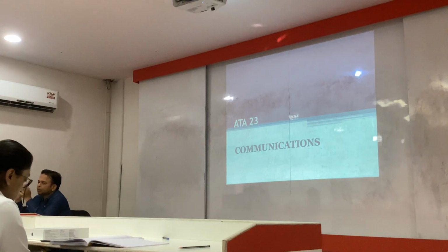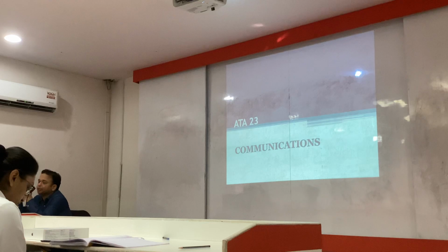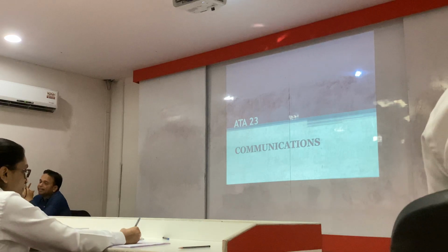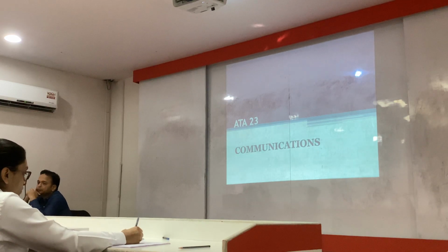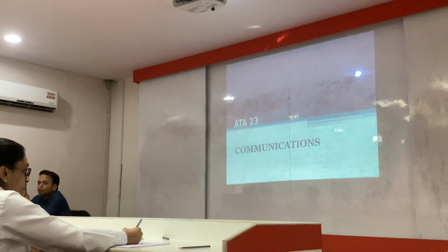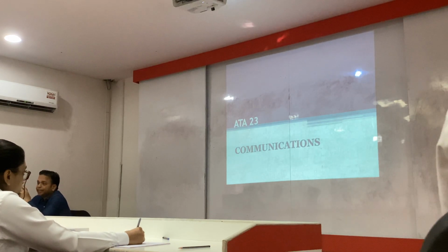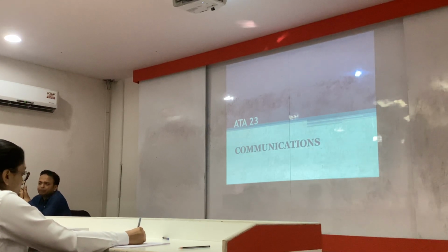Suppose with what all parties you are supposed to communicate? ADC. So let's discuss first. ADC. Okay, ADC. So what channel you are using? VHF or HF? Either. Okay, VHF, HF channel use it. Then cabin crew. What are the options available to talk to cabin crew? Intercom or PA. Anything else?